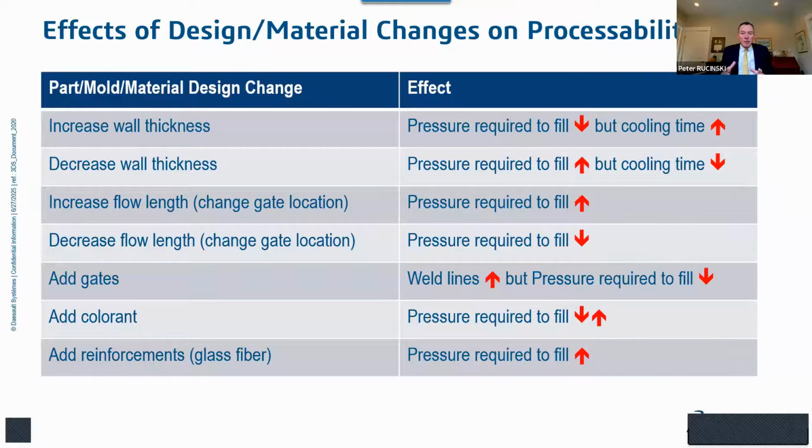So now I'm going to have to make sure that I don't exceed the maximum injection pressure capability of my injection molding machine. But since I made my part thinner, it doesn't take as long to cool. That's going to decrease my overall cycle time. This list could go on and on and on, but jumping to the bottom, if I add colorant to